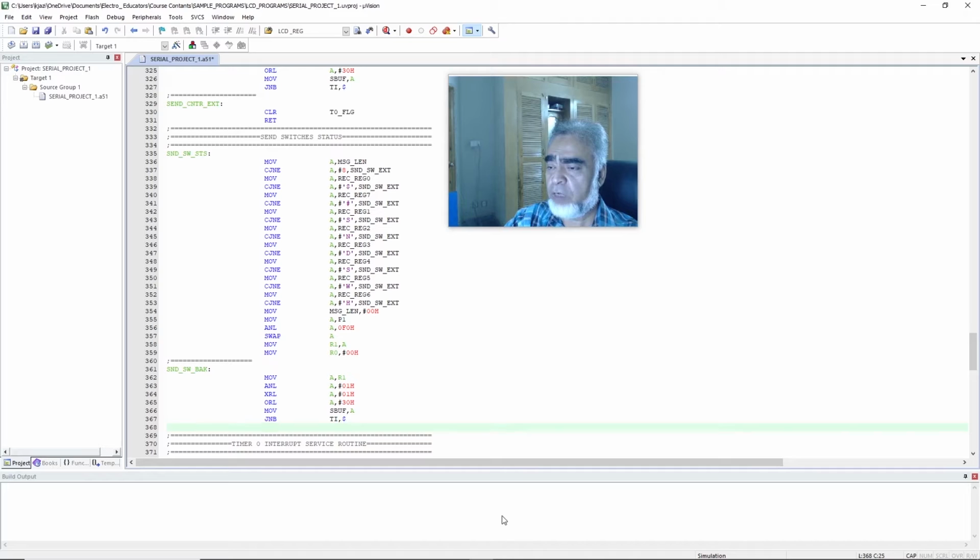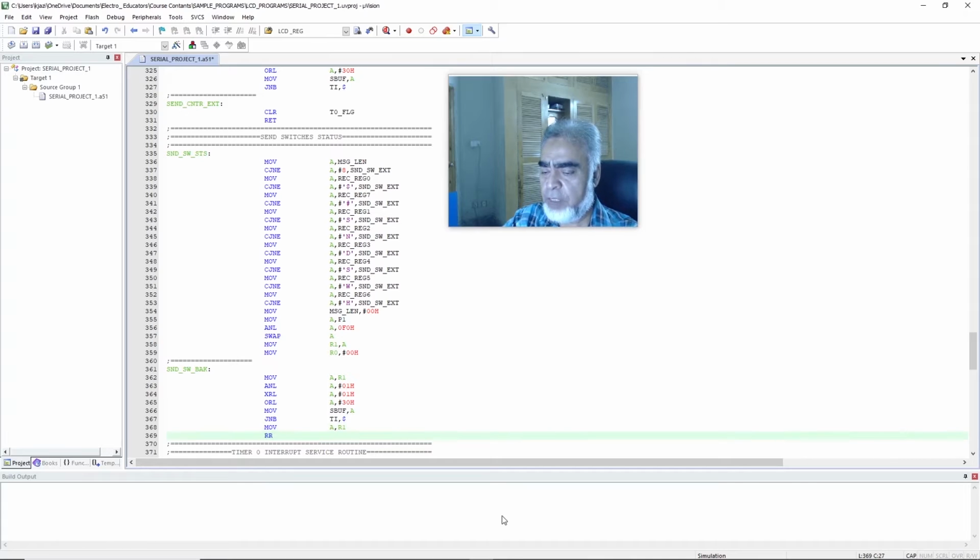And now we'll move the value of R1 to the accumulator once again to check the status of the second bit. So here we will write MOV A, R1, and here we'll perform the operation, that is rotate right accumulator. So here we will write RR A. It means we have moved the status of the second switch to the least significant bit position.